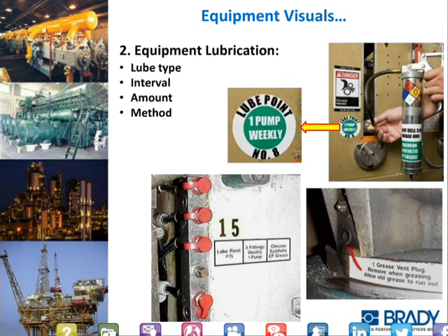The visual in the lower right-hand corner was an interesting case example in a plant we ran into out in Nevada a number of years back, where they had lots of pump damage, motor damage, bearing damage because of over-lubrication. And we found out from just a good maintenance practice, they weren't removing the vent plug to allow the old grease to run out. So for years, about 5 years, they've been pumping grease in there without taking out that vent plug. So the grease was actually filling up into the windings of the motor, swelling, expanding, and causing motor problems, and also going down into the pump itself.